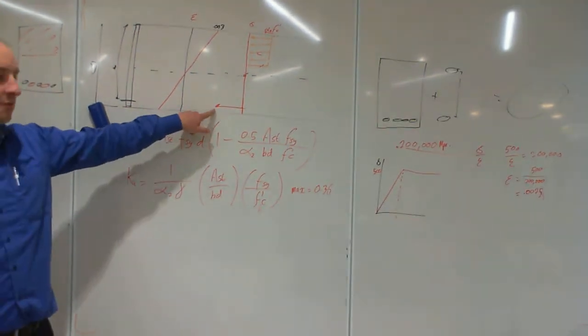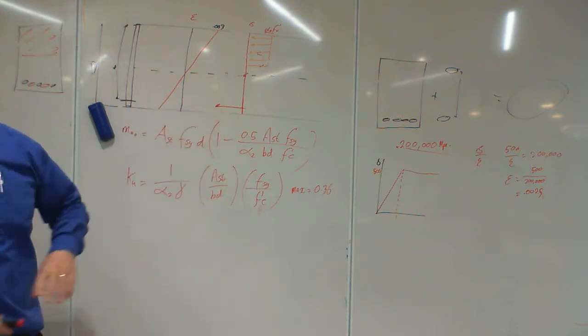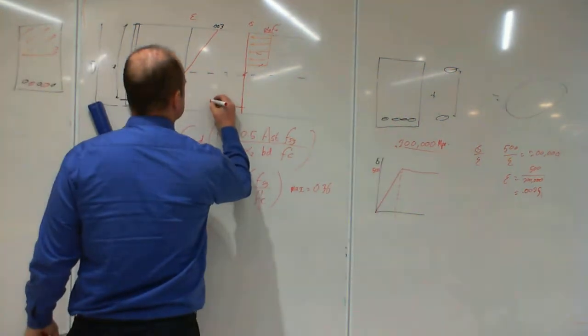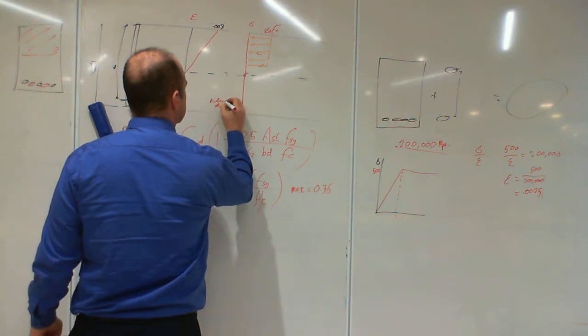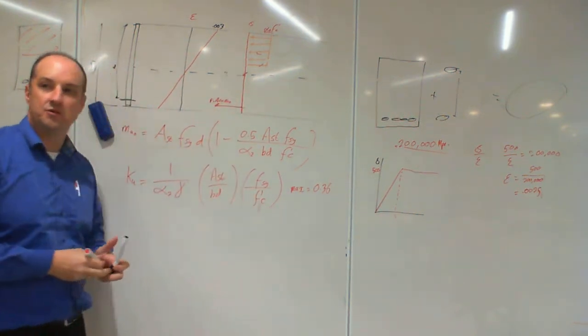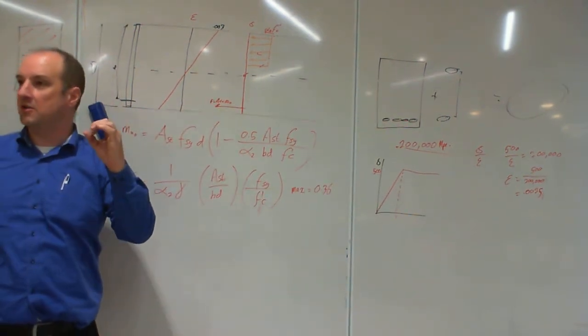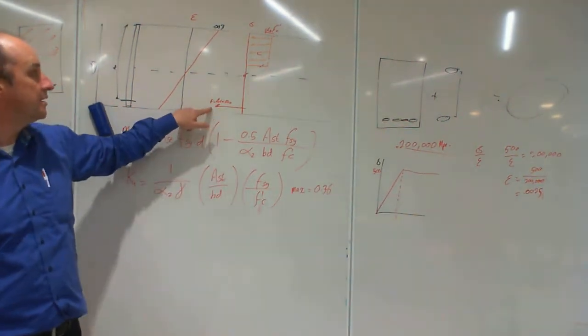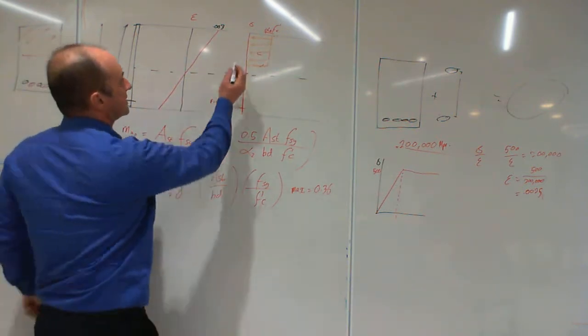Okay? If you want to know why that's the case, I can go into that later, but the bottom steel has definitely yielded. Alright, go with me on that. So the force there equals the area of the steel times 500 megapascals. The area of the steel, I'm talking about literally the cross-sectional area of the steel bars you put in. Alright? Now up here we've got the force of the concrete, and we're going to add some top steel.